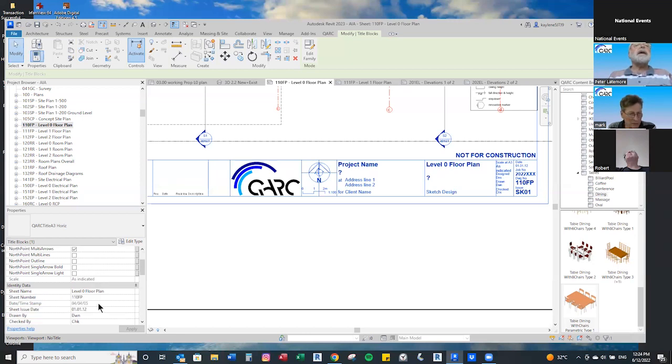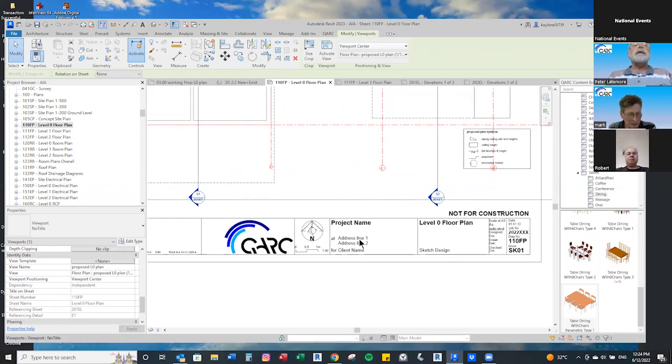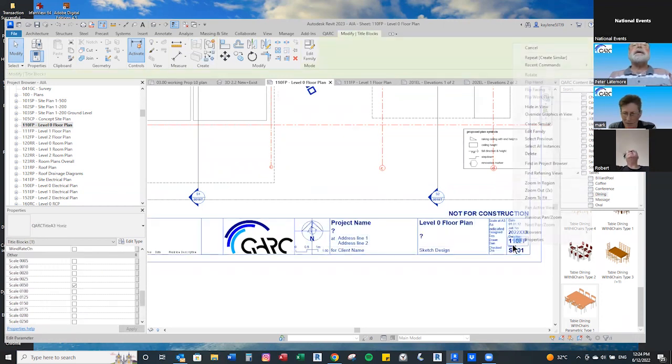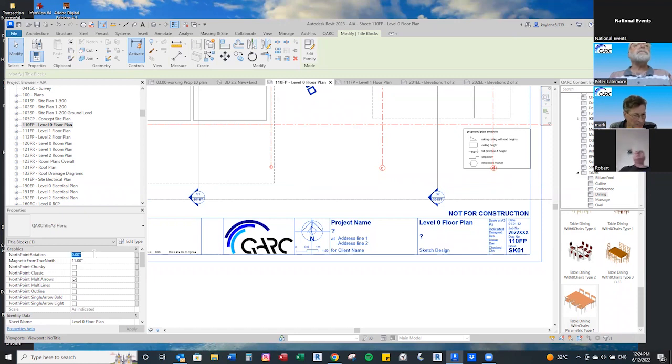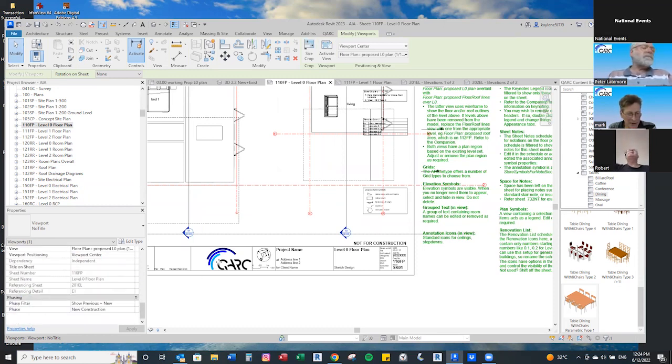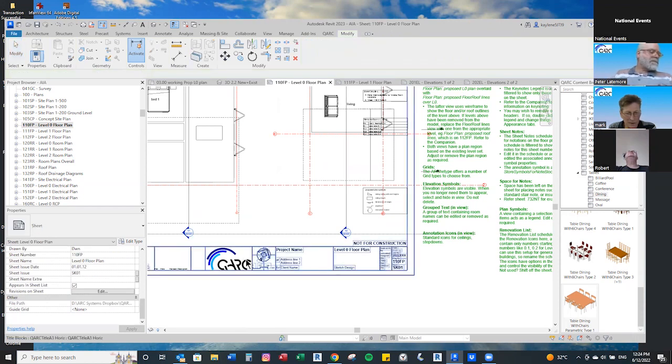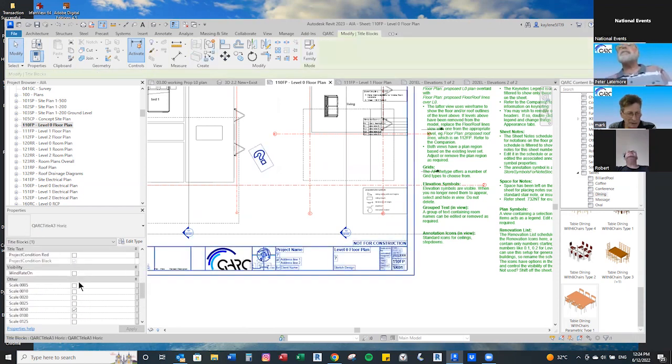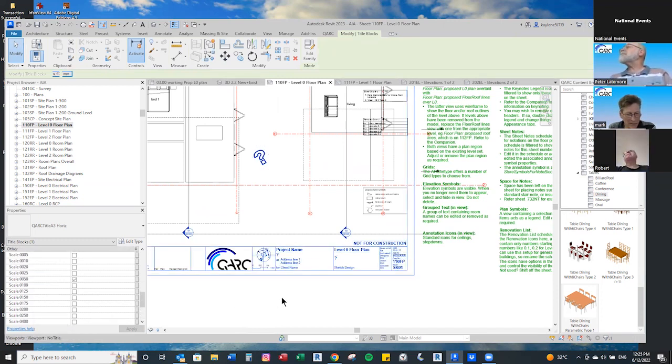Yeah, and here's Kayleen just showing you. On each title, we have a whole pile of preset scale bars waiting for you to just quickly tick and flick. So again, I've got some really odd ones. You'll notice in there, 1:25, 1:400. I put everything on an A3 sheet, and so I just keep coming up with different and odd scales. You're not supposed to scale the drawings anyway. So I want to fit everything on A3, it just makes it easier on site. So the key to this is changing the scale by a click of a button, and changing the orientation by typing information in.